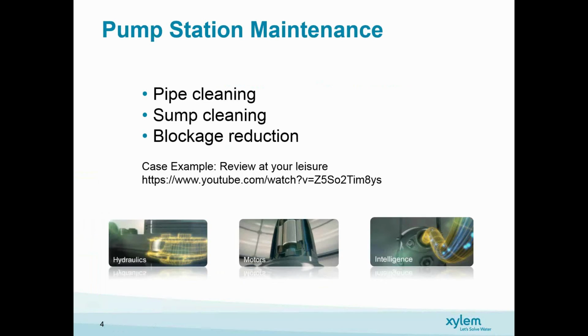The whole idea with the Experior package is to reduce your pump station maintenance and to save costs to the end user. Some of the points we're looking at there are the pump cleaning, which will clean the pumps and reduce your maintenance costs in the long term. Sump cleaning as well. What we're trying to do there is clean the wet well and reduce any of those solid build-ups in the wet well, the greases, the fats, the rags, which will eventually go into the pump and cause the pump to block, and reduce those callouts as well. And also the energy saving side of the Smart Run.